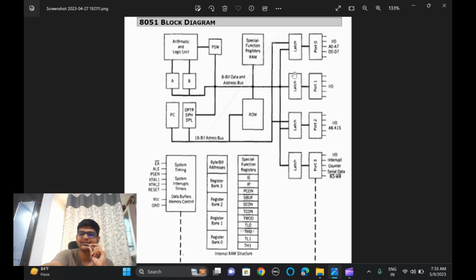Just like that happens with the 8051 processor or the device connected outside. Suppose that device started fetching the information and suddenly realizes it has missed something, and it comes back, but that information is not available at that time because you have already fetched it. Then what is there to store that information until the process is completely done? So the latch stores the data sent by the processor until the externally connected device has done its process successfully. As soon as the device has successfully fetched and executed, the latch will lose its data.